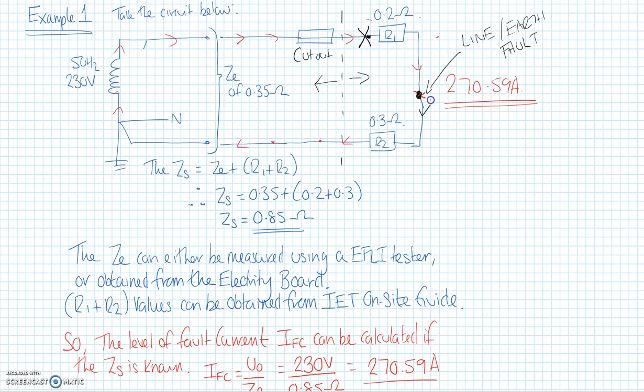What we want to happen here is we want this live current, this fault current, to travel down our circuit protective conductor, which is our CPC, which is our R2, to our main earthing terminal in our installation, and then outside. Then we go down the distributor's earth all the way back, probably on a lead sheath, because this is a TN-S arrangement. It's a TN-S arrangement because we've got a separate earth.